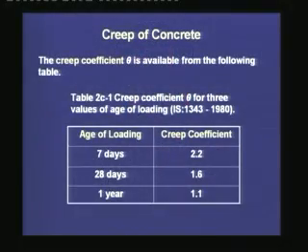What we can see is that if the age of loading is 7 days, then the creep coefficient is 2.2, which means the ultimate creep strain is more than twice the elastic strain. If we load it at 28 days, then the creep strain is 1.6 times that of the elastic strain. And if we load the structure after 1 year, then the creep strain is slightly larger than the elastic strain. But in all of the cases, the creep strain is higher than the elastic strain.